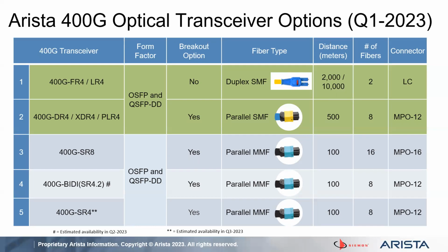So the FR4 is duplex single mode, and the DR4 is the single mode parallel. On the multi-mode front, I'm going to talk a little bit about that. Currently available today is the SR8 from Arista. That one utilizes the MPO16 connector that I mentioned. There hasn't been a whole lot of market adoption on that, just because of the non-standard interface.